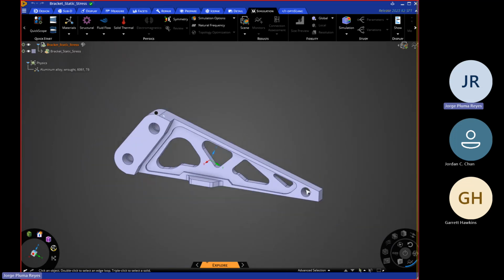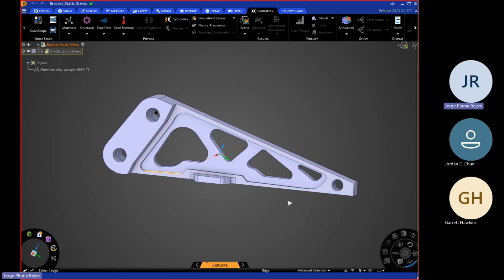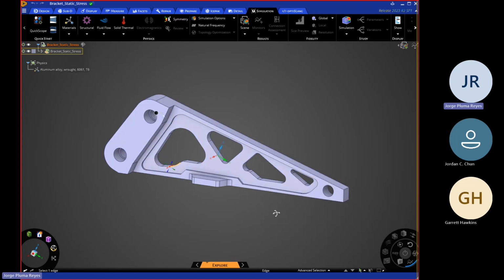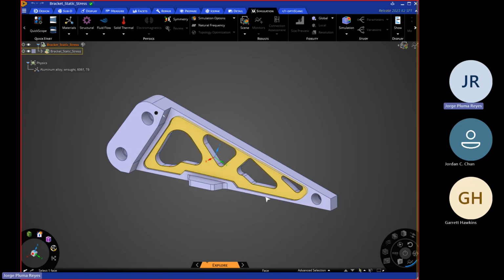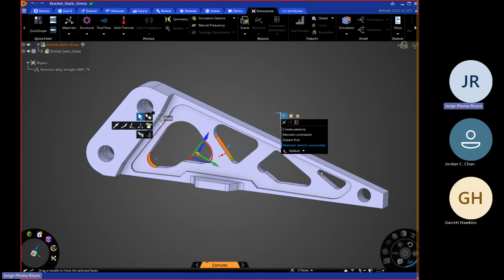So a couple of things here. Something that's very unique in Discovery, as opposed to many traditional CAD software, is that we're feature-based modeling, which means we're not tied to, let's say, a sketch when trying to make updates. That's very useful if you're trying to make quick changes, explore your ideas, and put them not onto paper, in this case onto Discovery. So for example, if I wanted to take that in here and take this in here and move them a bit, I can do so freely. Let me update this orientation here.